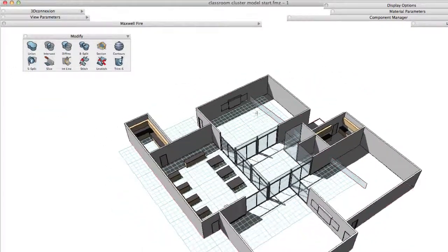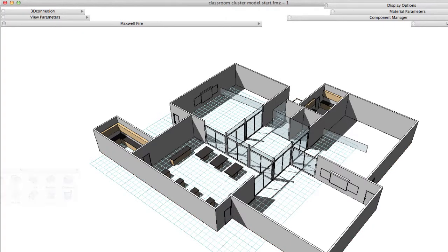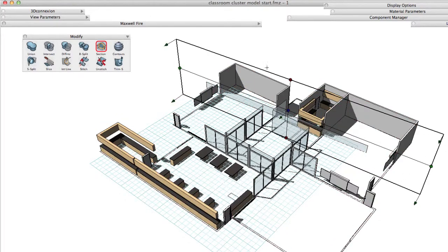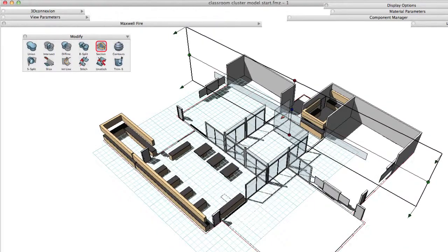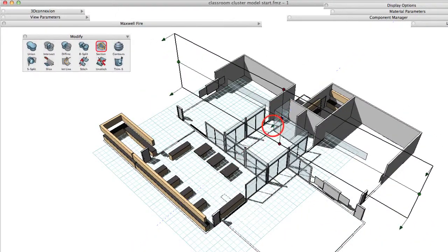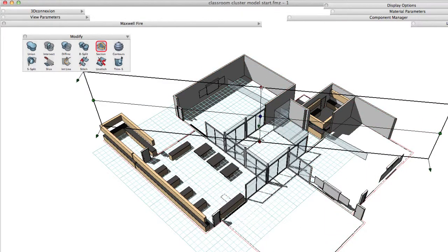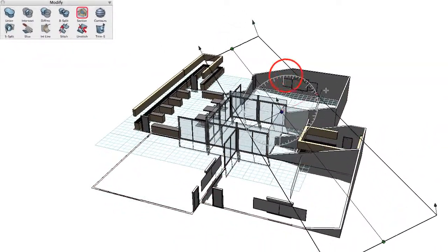And so all you really need is a sliver of a plane, any plane, to slice through a model. So let's see, I'm going to select my walls again, hit the section tool, and then hit that plane. And you can see it still slices through the entire object that I pre-selected. Okay, and again, of course, I can move that, I can rotate it. I can rotate it the other direction as well and go that way.